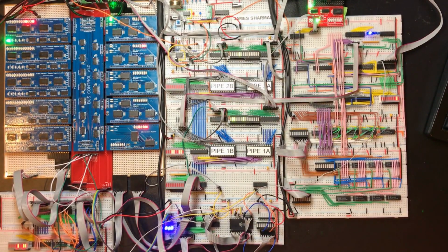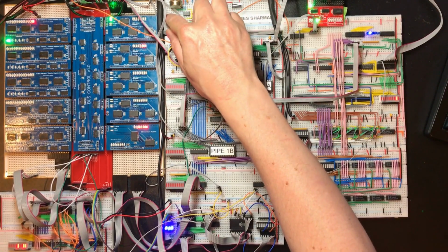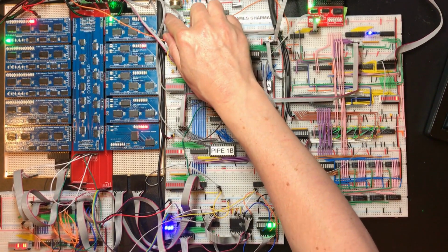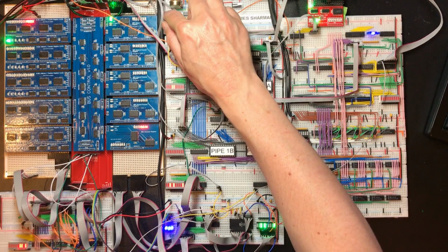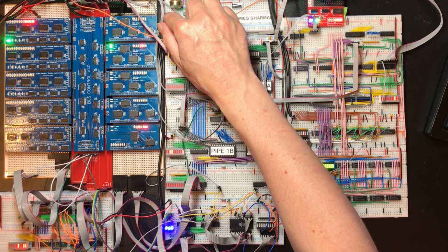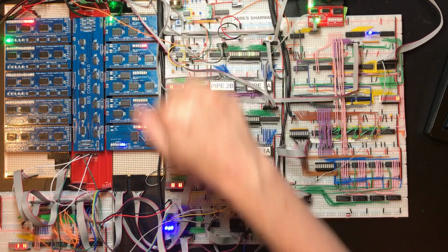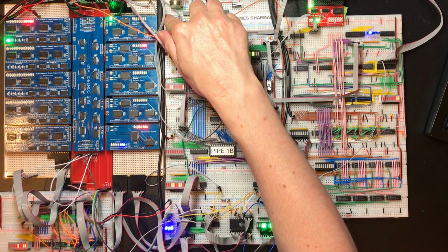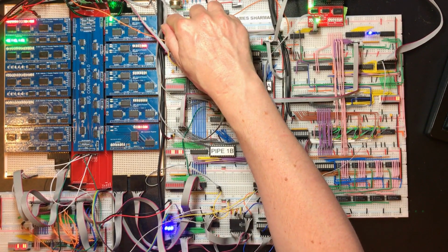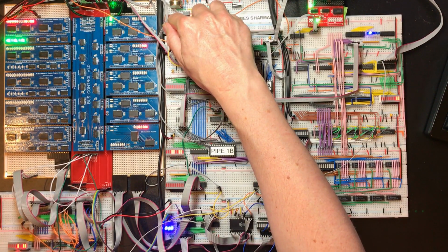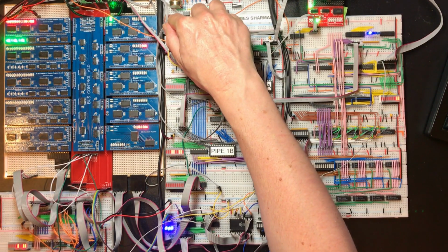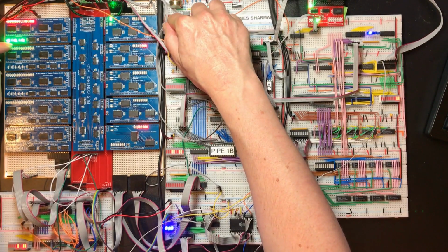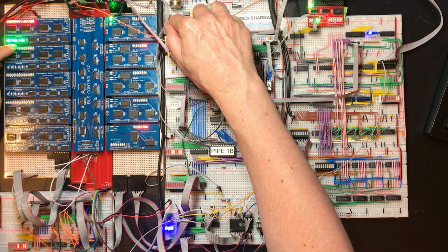Okay, now this is odd, and I suspect this is something that we just have to live with and work out how to deal with. So let's clock that all the way through till we get the jump again. Right, so when I clock again, I'm getting that jump if not 0. So we've loaded the value of TL into the program counter. But we've got an increment here.